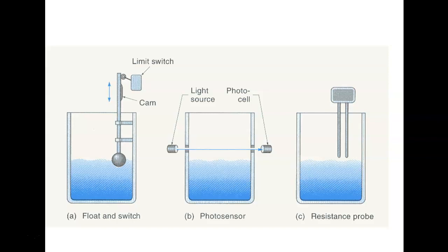The other one is just a photoelectric sensor. It's shooting a beam through here, and when the material gets up and blocks the beam, it would tell us. So this would be kind of like our reflective sensor that some of y'all are having problems with. This one right here is true when the level is low, and it goes false when the level gets up above it, right? You understand? Some couple of y'all had to come in and swap your contact around.